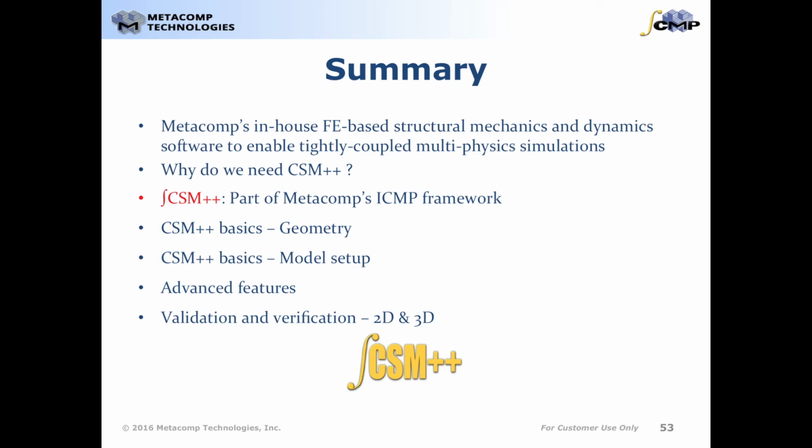Next, we presented all the options available to the user regarding model setup such as analysis type, solution type, modeling type, and solver types, along with the detailed list of modeling capabilities. We have also looked at some of the advanced features supported by CSM++, such as choice of update methods for nonlinear analyses, choice of enforcing multi-point constraints, and specification of large overall motion and follower forces. And finally, we have provided a collection of 2D and 3D structural mechanics validation cases to provide a glimpse of the kind of analysis and the quality of results users can expect from CSM++.